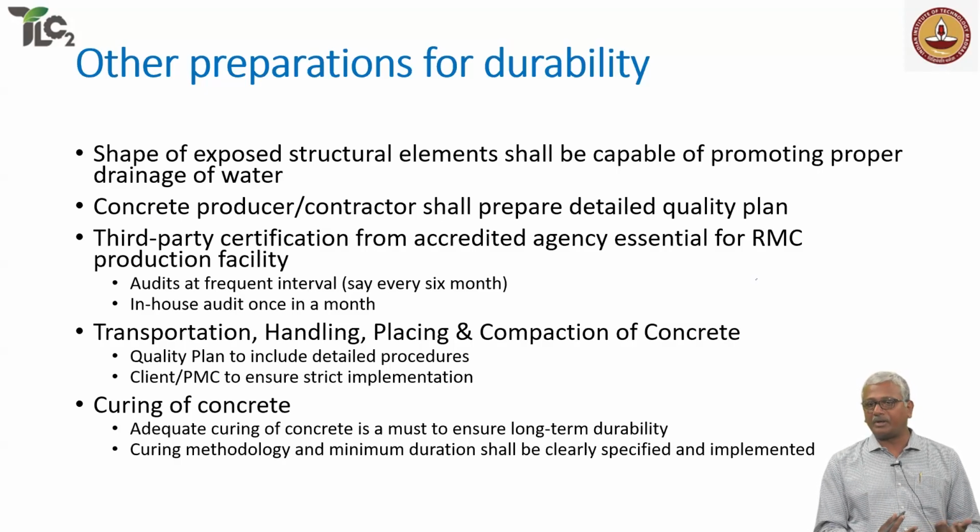If your concrete quality is bad to begin with, what can you do on site which can help, right? Transportation, handling, placing and compaction. These are aspects that need to be paid attention to. Again, this is happening mostly without any engineering supervision. This is where most of the problems happen. So that means we are disseminating to the last line of people who are handling our project.